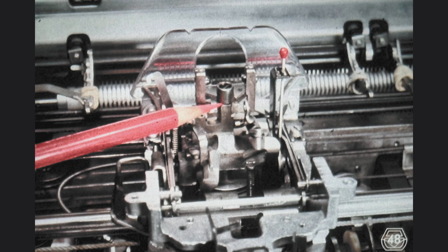The rotate shaft extends all the way through the rocker, and its end play is determined by the positioning of the rotate pulley, as we will see during the exploratory disassembly a bit later. All we need to do to obtain 1/10 of 1 millimeter of end play is to loosen the set screw for the rotate pulley and adjust the position of the pulley up or down on the indicated shaft.